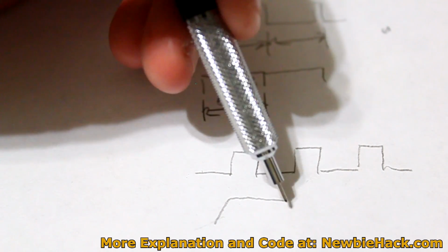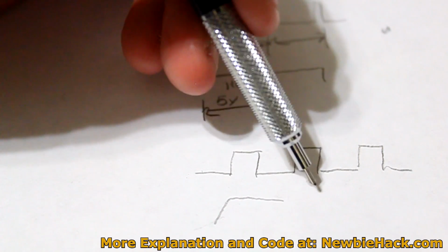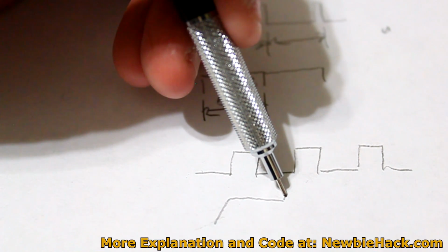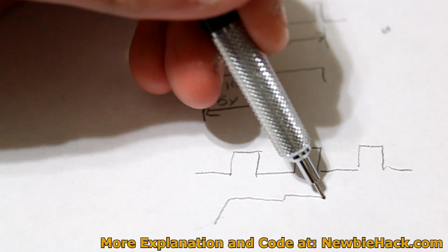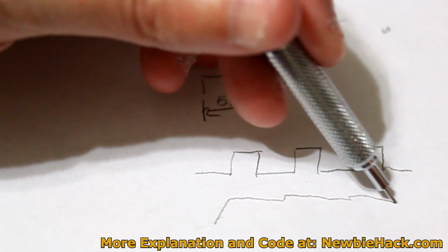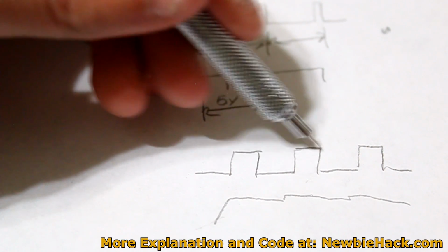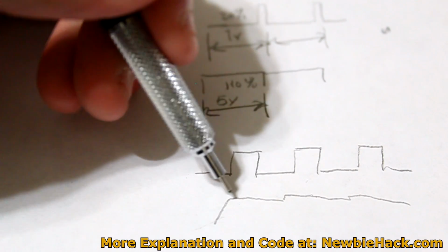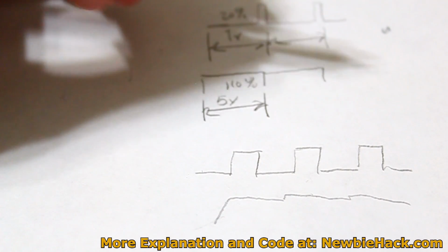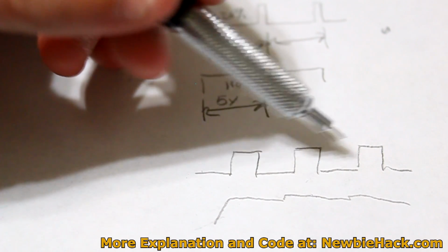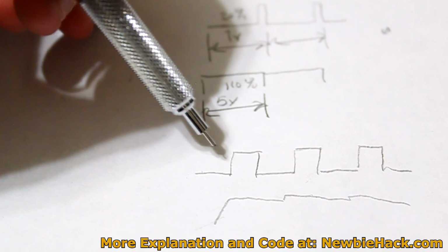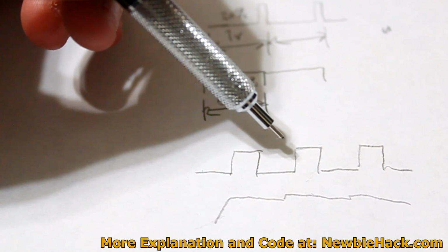But it won't go all the way down to 0. It'll catch the next wave of pulses, and it'll come up a little bit and go back down, come up a little bit and come back down. And it'll most likely be flat between where the pulse is, the length of the pulse. So you can start to see that there's now a line. Just by adding capacitors, you can create an actual analog voltage out of the pulse width modulated signal.